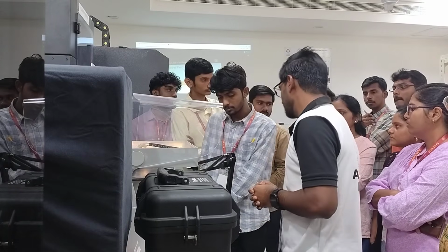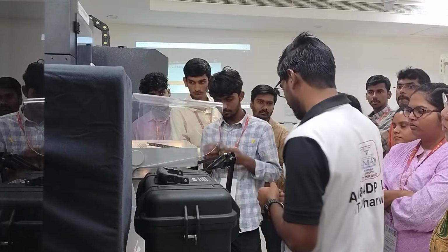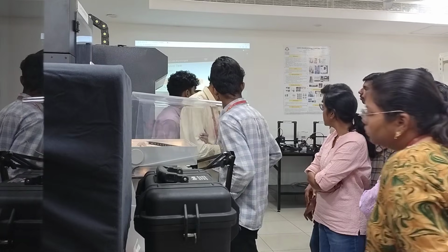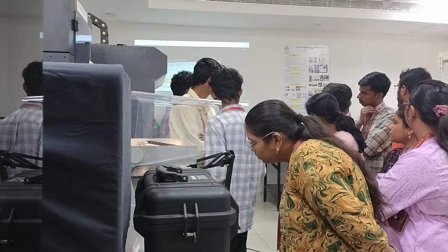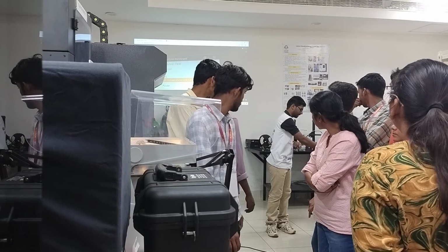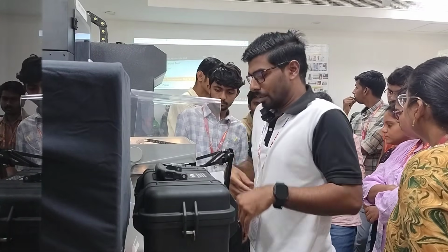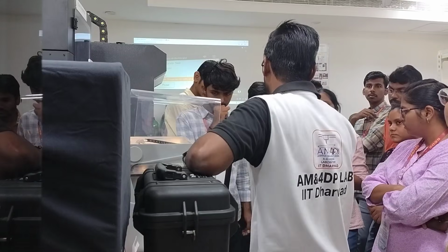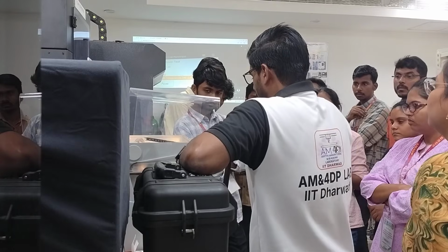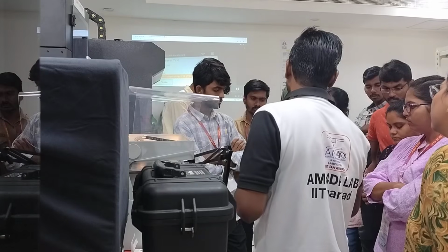The fiber you're placing will also get heated? Yes, it gets heated. This is the carbon fiber. These carbon fibers are also heated to a high temperature, I think 330 degrees Celsius. On heating it becomes a little bit soft, so it is actually infusing with the plastic material when it is heated.